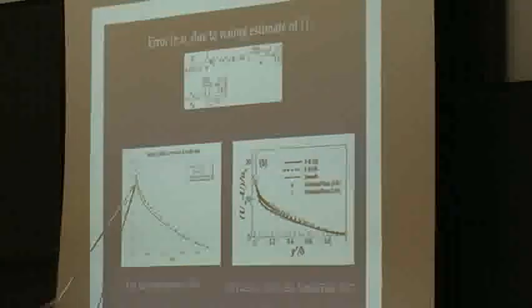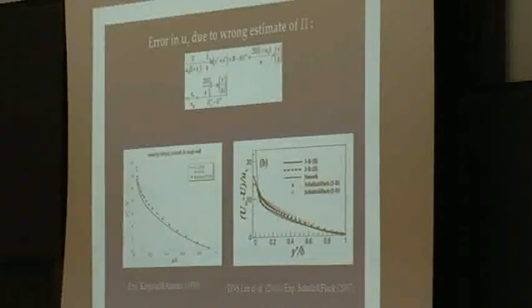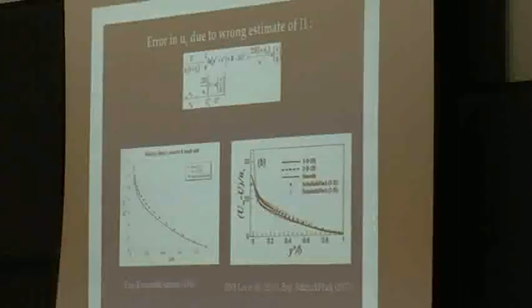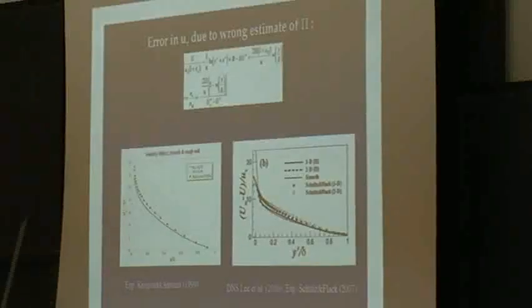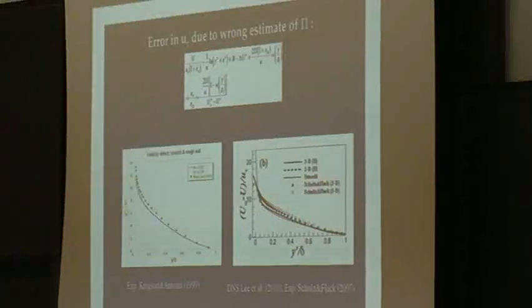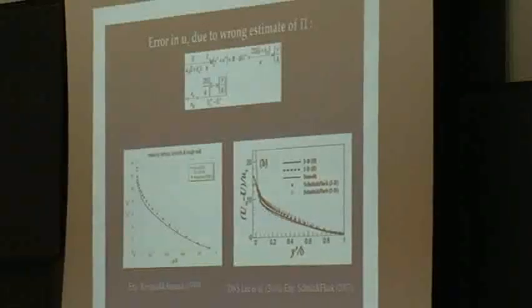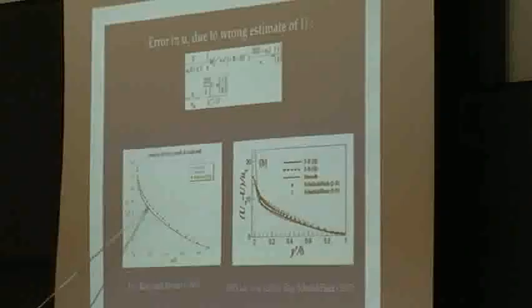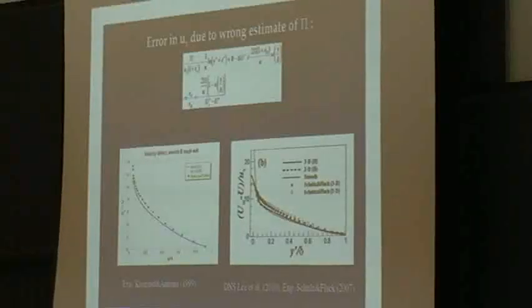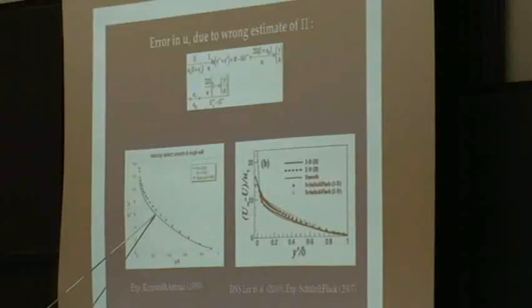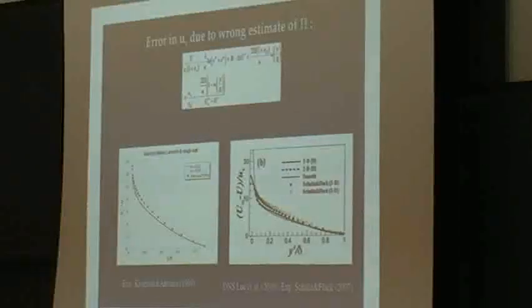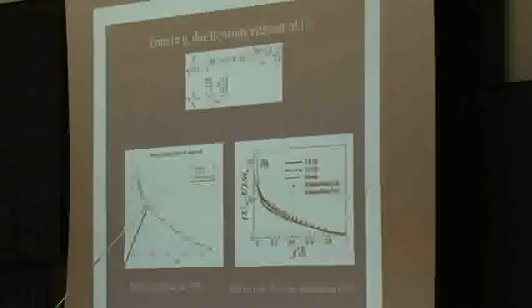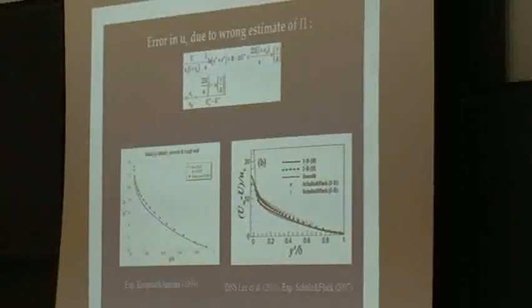But if you have different pi's, you will see the difference in the velocity defect. I plotted this more or less standard function that you will have for a smooth wall with a pi as wake strength of about 0.55, and compare that to my measurements of a wake strength of about 0.7. So I get this curve. Now, it would be very simple for me to make my data match this one by changing the friction velocity. So you see that there's a link between what you get for pi and the friction velocity.